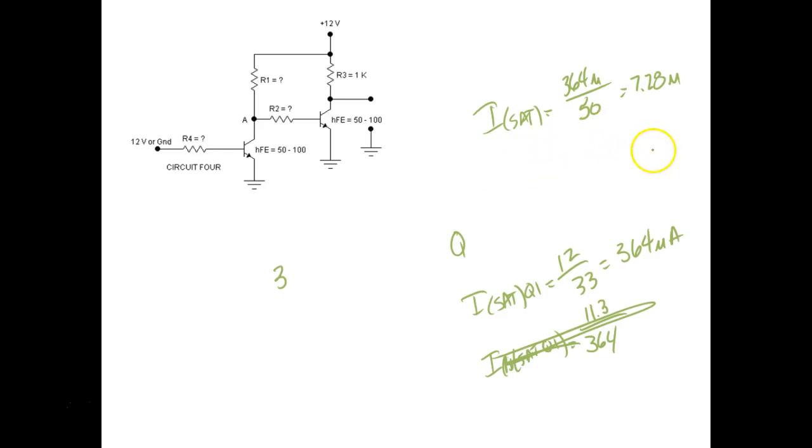Okay. Then R2, I'm sorry, R1, I'm sorry, R4 would be equal to 11.3 divided by 7.28 or 7.3 micro. You can round up, but don't round down, because we're trying to move away, right? So what's R4 equal to? Sorry, guys. 1.5 meg.